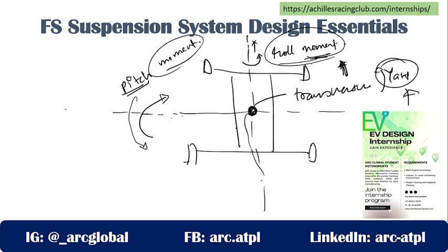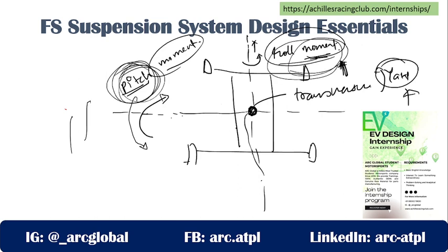My dear friends, of all these three moments, you have not provided the input for the rolling. You want your vehicle to move forward. You want your vehicle to corner. Roll occurs because of certain disturbances on the road. I want to accelerate my vehicle. I want to decelerate my vehicle. But pitch is the net outcome of the input that you have provided. This is not what I desire. I just want to accelerate, I just want to decelerate, but this is something that happened. This is a byproduct of my acceleration, a byproduct of my deceleration, a byproduct of moving my vehicle on an irregular surface.